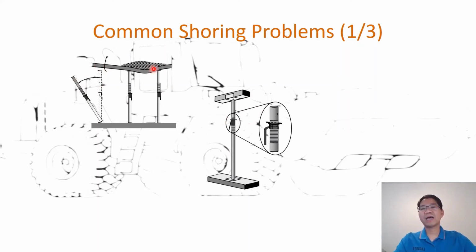So if we have the slab here, and this shore, and you can see that it is not tied into the structure or the beams of the formwork correctly, then if we place concrete in one place, because this is the formwork, it's easy to deflect or bend. And if it bends here, with nothing tied to that formwork, it will fall out, and that will cause a cascading effect. If the support here is not enough to hold this shore, it will collapse the whole temporary structure and the formwork. And of course, there may be casualties if workers are working on that slab.